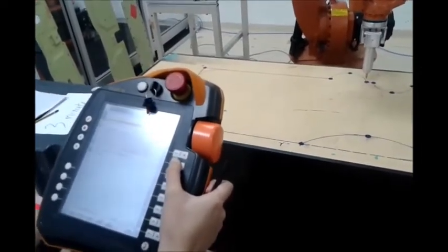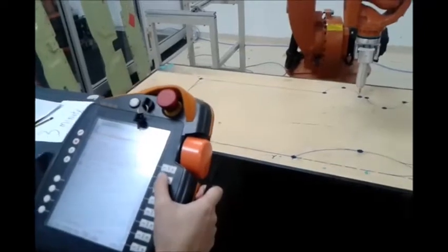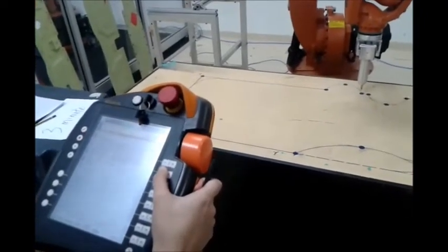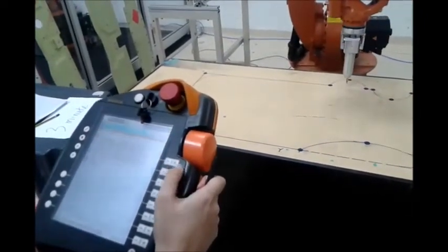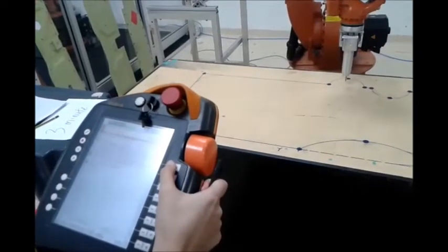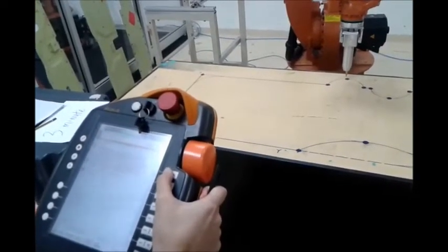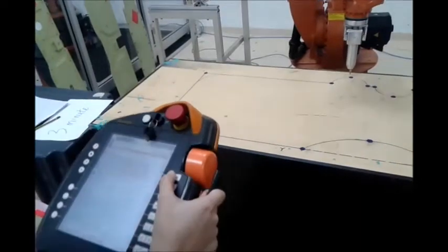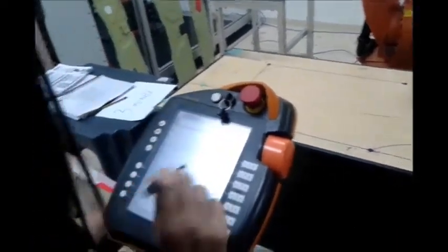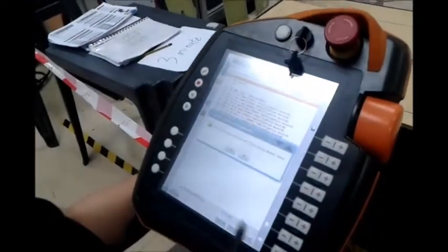So now it's again circular motion. So I go to the center point first, and then x-axis. Okay. So this is the center point. So command and I choose the circular motion and teach auxiliary.